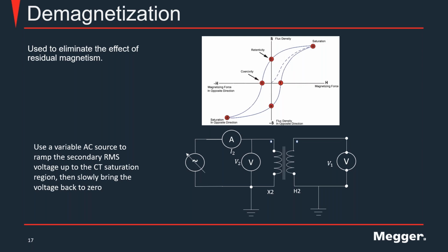You don't need to worry about demagging the transformer core, but yes, as has been mentioned many times before in the presentation and during questions, you do need to demagnetize the core of the CT you're testing if you run any of the DC related tests, winding resistance or insulation resistance. All right, Abel. Insulation resistance, I'm sorry, it's not ratio. Oh, no worries. For insulation, okay.